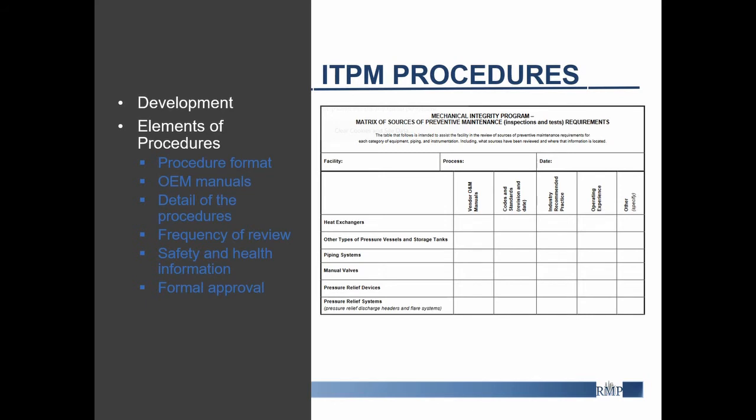We also get questions on how detailed the procedure should be and how much of a maintenance technician's training can be relied upon without generally high detailed procedures. In general, simple tasks such as lubrication do not require detailed explanation in the maintenance procedures. However, the level of detail must be consistent with the complexity of tasks to be performed and the level of skill of the maintenance workforce.